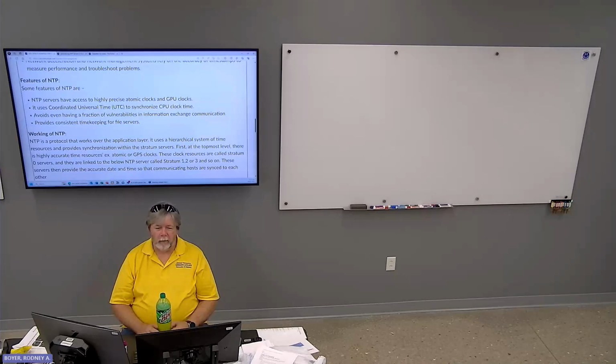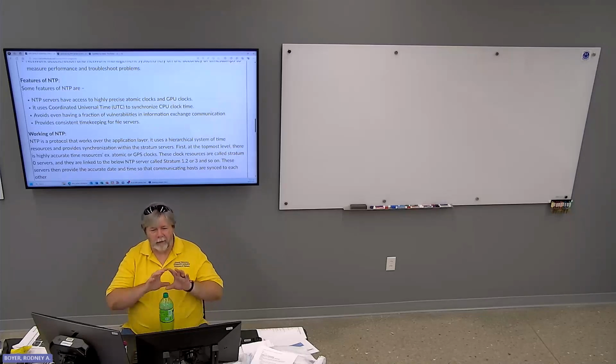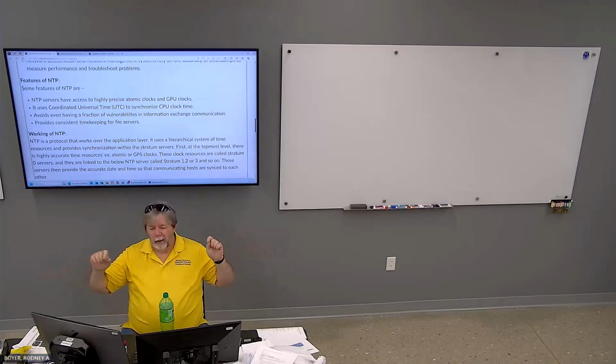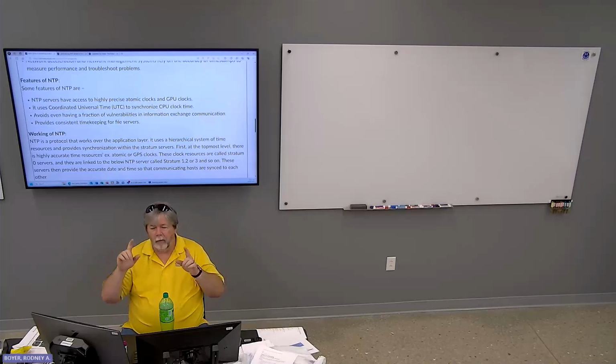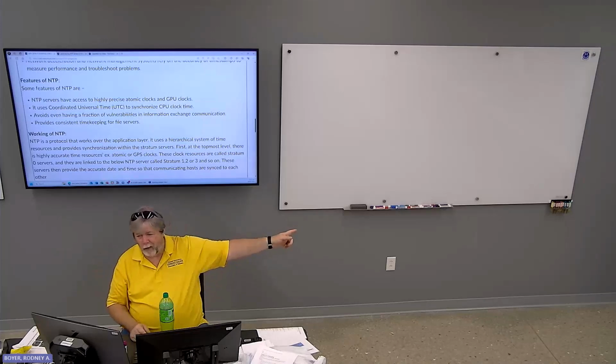Well, whenever you're talking about a data historian, SCADA, it takes a sample every, whatever their program time slice is. It records all the values that it's supposed to know about. And you do that on every piece of equipment in the building. If they're all synchronized to the exact same time, then you can know when this problem happened over here, we can trace everything back and find the root cause was from something way over there.